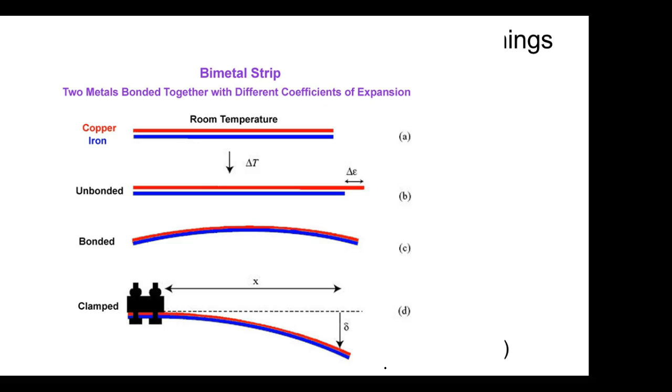So that's why when you wire up, if you were an electrician and you did wiring, you need to know what gauge wire to pull. I understand that if you pull the wrong gauge, if you pull a wire that's too big, then you waste a lot of money. If you pull a wire that's too small, then the wire's probably going to get hot. And then once it gets hot, its resistance goes up, which is not good.